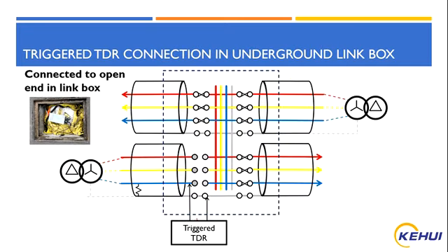Another method of obtaining an open end is to position the TP23 TDR unit at a normal open point in a link box. In this case, the cable is backfed from its normal supply point, such that it remains live and the supply is maintained for the consumers.